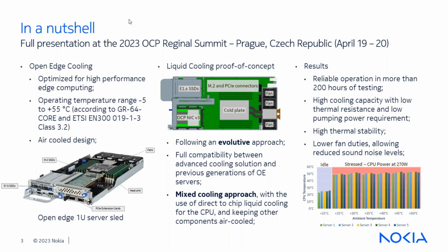Yeah, we can have a thermal radiator on the outside of the system, and then, for example, one configuration would be that we have an external system that is rejecting the heat to the environment, so that we can maybe use the possibility of free cooling there. And then, instead of having those powerful fans, we could expend a little bit less power in the system, but also be less dependent on the cooling of the environment itself. So for the system as a whole, we reduce the dependency on the cooling of the site.